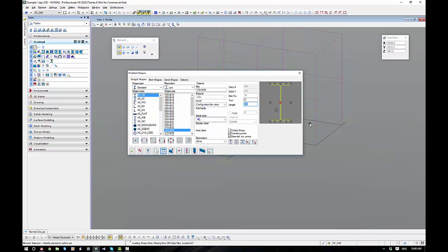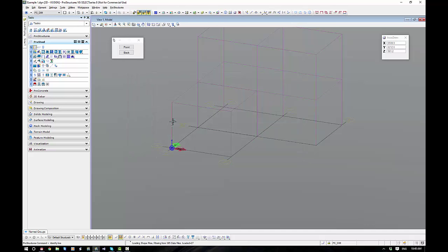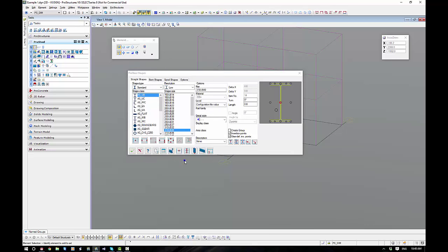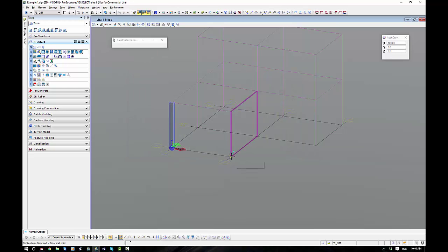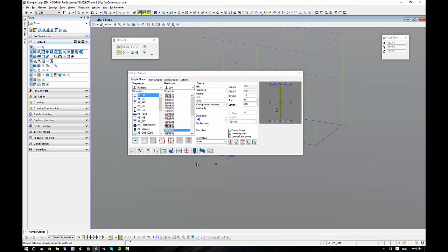All right. We have numerous ways that we can put these little guys in. We can put them in by a line that we created, sort of like the work frame. We can just pick a line on the work frame and in it goes. That's all very simple. We can put it in also by 2 point, where we nominate the start and we nominate the finish. Both are very simple, both very effective. If you didn't have a work frame, you'd use the 2 point. There's no real constraints to where we put steel.